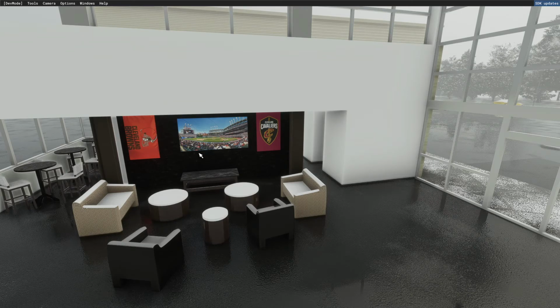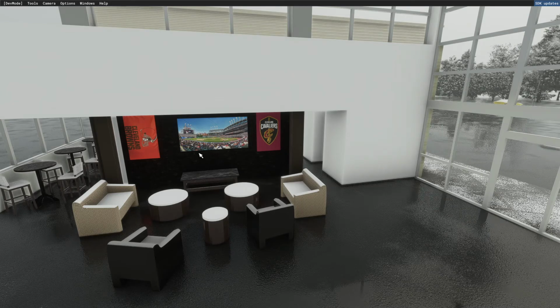So in order to stop rain and snow from going inside your buildings, you need to put a cube box around whatever object you don't want it to rain and snow inside of. And you want to use the Microsoft Flight Simulator texture parameters and choose Environmental Occluder, and then export your model, rebuild your package, and then you no longer have rain and snow inside your buildings.